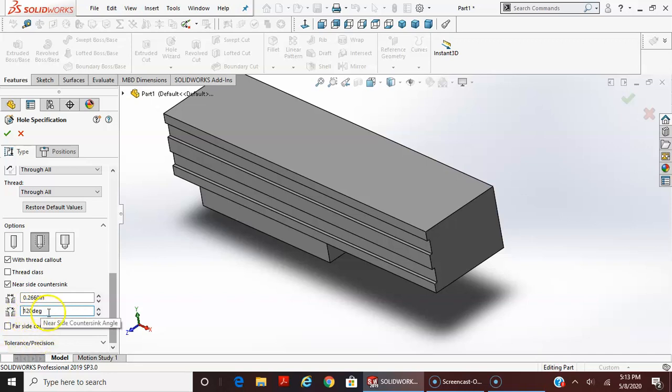And this angle, when you're manufacturing, really applies to the type of drill you're using, because there are different drill tips. The standard drill tip is 118 degrees, and if you use a 120 degree spot drill, it's perfect and allows for the tip of the drill to start cutting within the spot drill with 1 degree clearance on both sides.